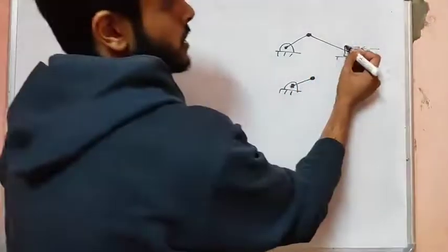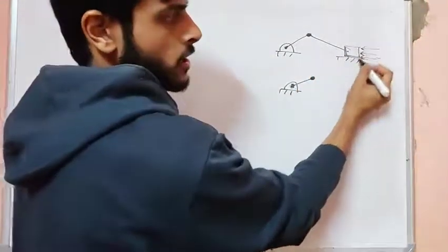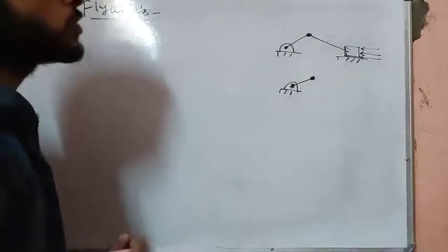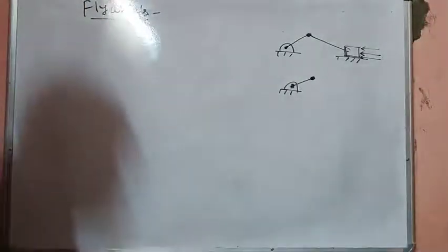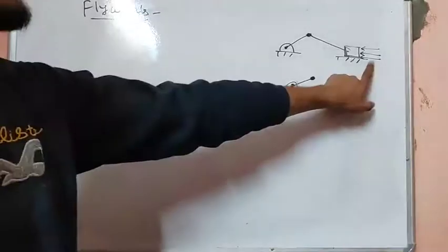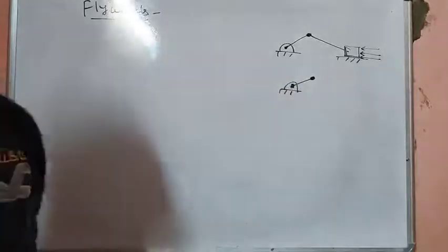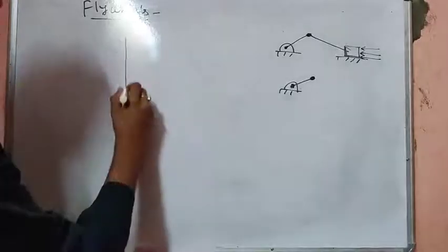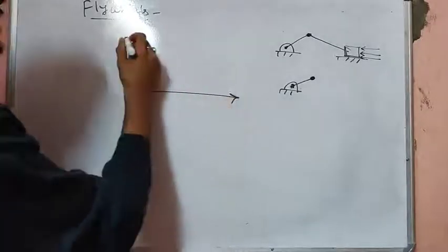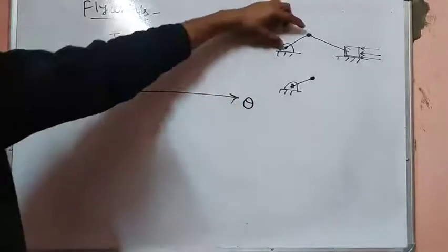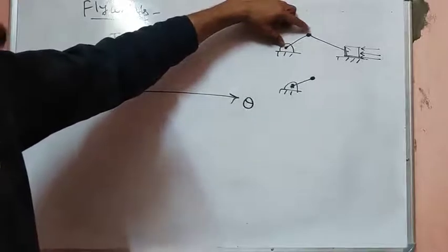Because of the gas pressure over here, this gas pressure does not always act in the mechanism in an engine. In an engine there are basically two stroke engines and four stroke engines. In both types, the gas pressure produces the power, and the power stroke happens at only one of the strokes. Let's say we consider a four stroke engine, so we will have something called the turning moment diagram. T is a function of theta. This is the torque which the crank will be experiencing.